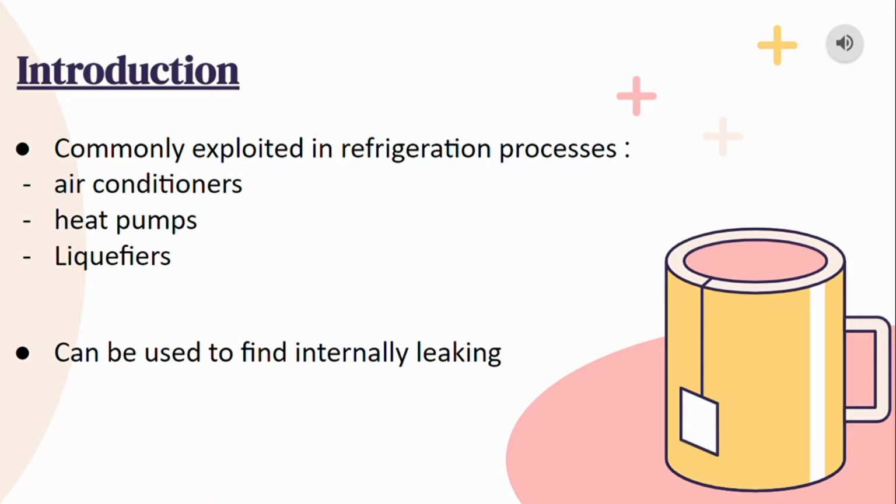In thermodynamics, the Joule-Thomson effect describes the temperature change of a real gas or liquid when it is forced through a valve or porous plug while keeping it insulated so that there is no heat exchange with the environment. This procedure is called a throttling process or Joule-Thomson process.